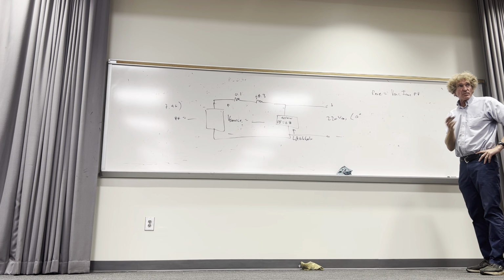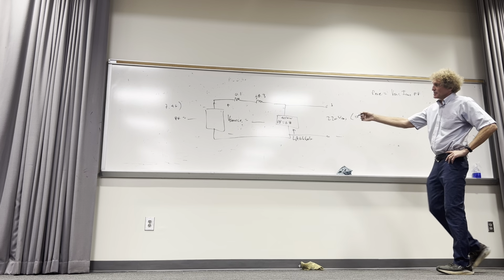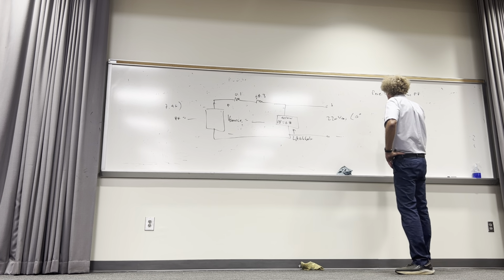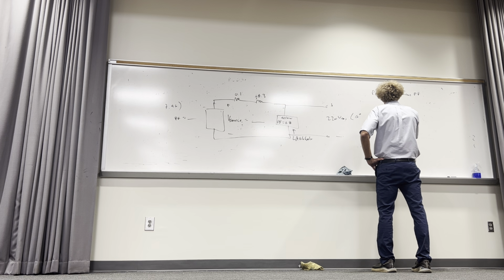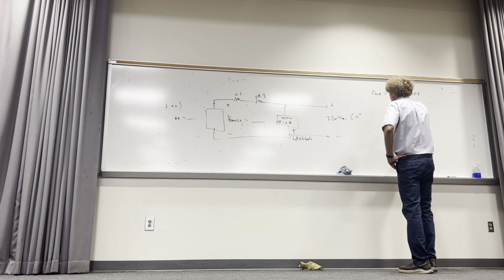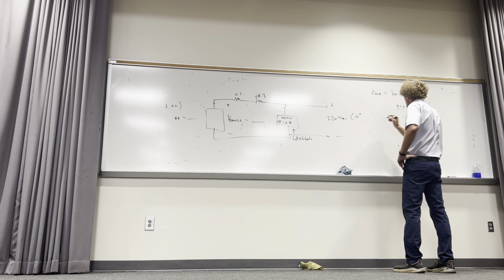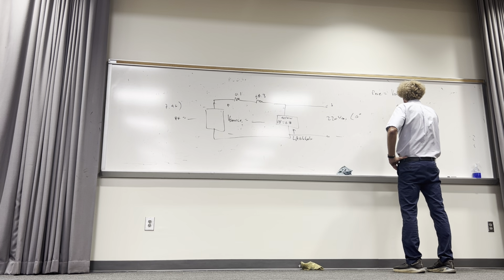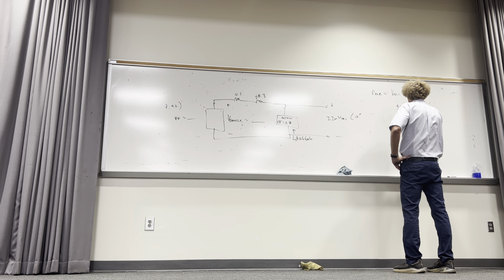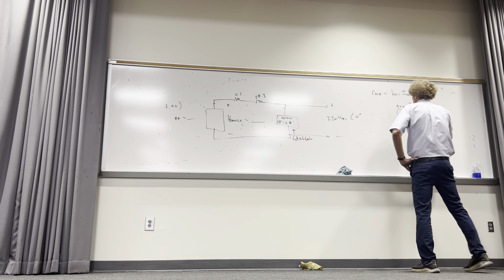Can you all follow me on what I'm doing here and why? How do I get it? Can you see 40 kW here? It's a little small. So I can take 40 kW and put it on this side, 40 times 10 to the third. Then I divide it by V_RMS, which is 220, and then by the power factor, which is 0.8. Now I get the magnitude of the current, I_RMS.